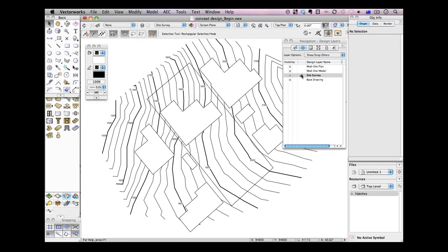This is a site survey, so you've got two methods of getting this information. One, use an image from something like Google Image or Google Earth, but the other one, the better one, is to get a surveyor to go on site and actually measure everything for you. Now my image is quite crude, and when I come to do my calculations of areas, there's a lot of errors that could be in there. A survey reduces those errors for you.